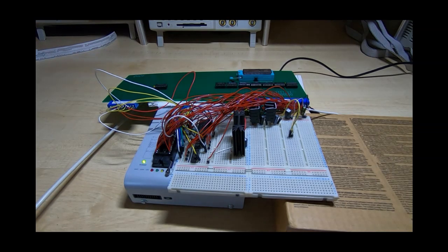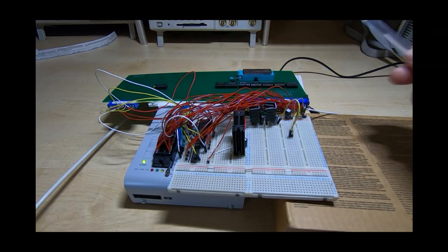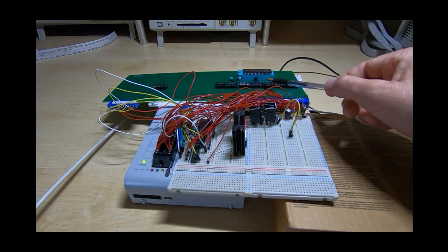Now if you've been watching the previous videos, then you'll know that the arrangement of the ROM card is fairly unusual in that the ROMs are 512 bytes each, arranged in pairs to give us a 16-bit data word. And that means that the addressing is not just a simple case of taking the address lines and using those to directly address the EEPROM. So what I've had to do is put in place some unusual decoding.